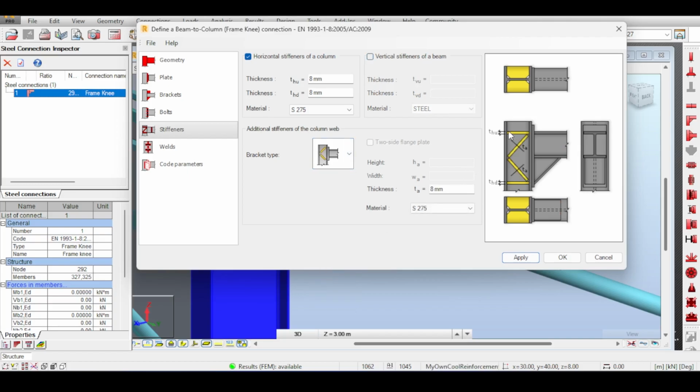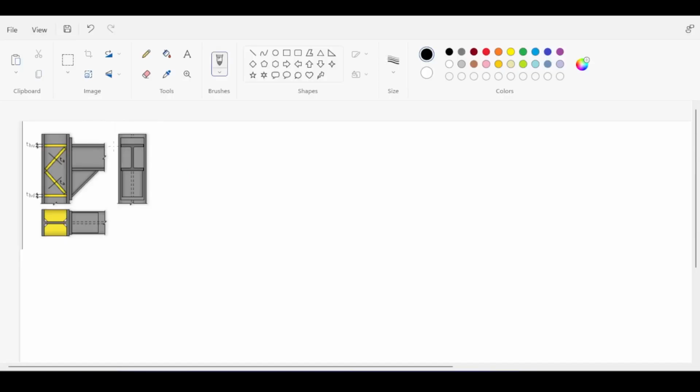next level. If the stiffener here is not enough, you could make a truss. It's not really a truss, but you can make a truss-like interaction between the top stiffener and the bottom stiffener to try to alleviate it. Let me explain this. Look, you have huge tensile forces being applied here because of the negative moment, and huge compressive forces being applied like